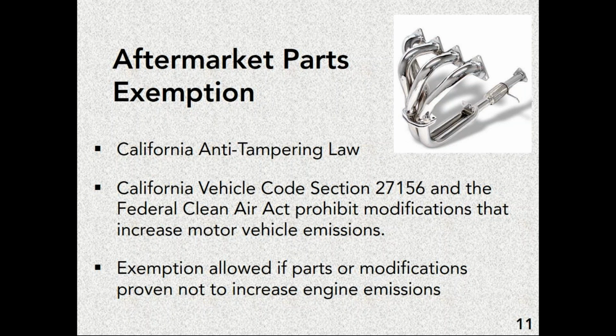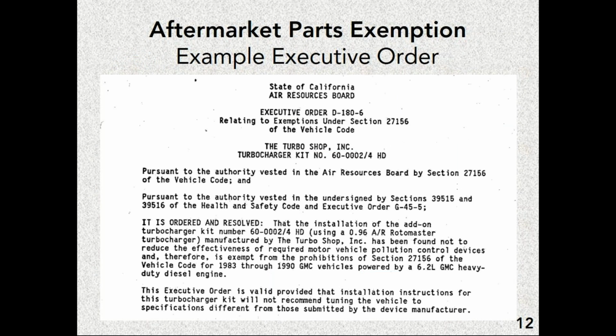So if you were just to buy one and put it on and not worry about it having any kind of certification that it does no damage to the emissions, and you went to do any kind of smog related thing, smog check, you would be failed even without measuring the emissions coming from your engine, because that particular component is not certified to do no damage to the emissions. So component manufacturers are required, if they want to sell parts for vehicle engines in California, to get these executive orders for each of the parts that they want to put for sale.